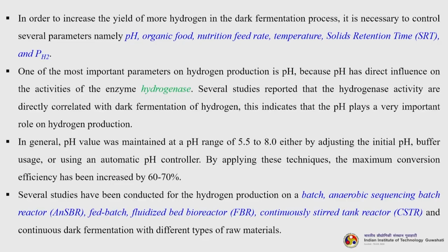Anyway, as I told you many times, pH always plays a very important role, whether it is a biological system or a non-biological system, especially when you are dealing with an aqueous medium reaction. Now, in general, the pH value was maintained in a range of 5.5 to 8, either by adjusting the initial pH using a buffer or by using an automatic pH controller. By applying these techniques, the maximum conversion efficiency has been increased by 60 to 70%.